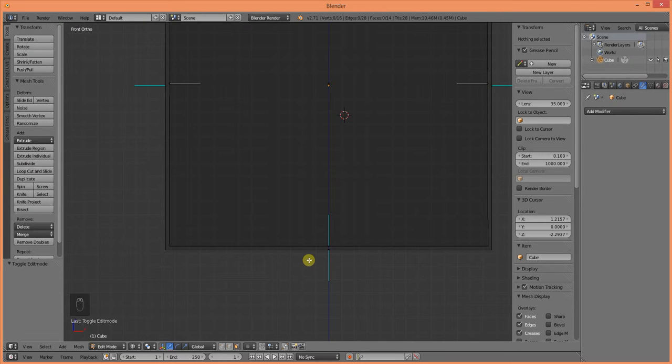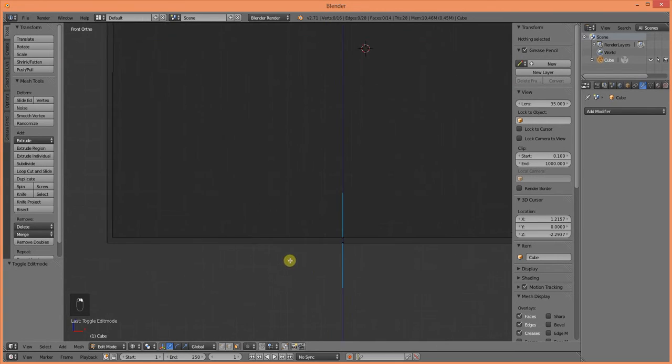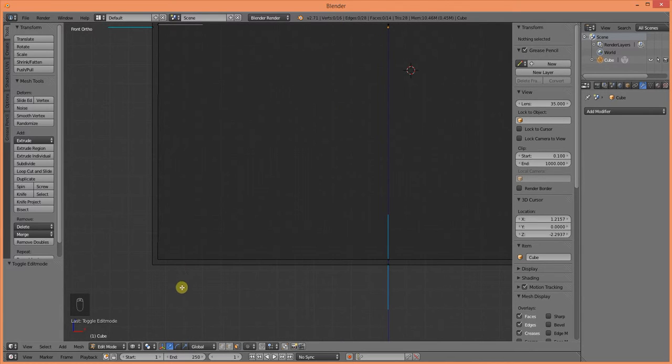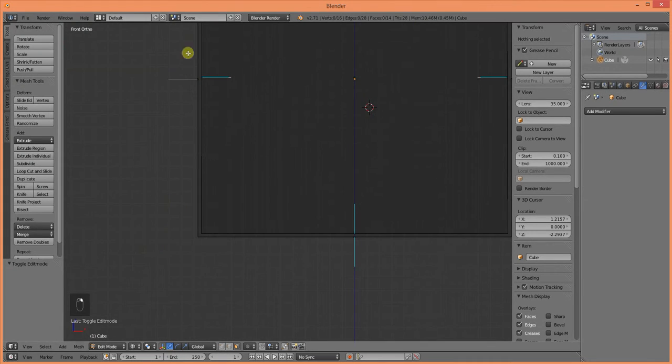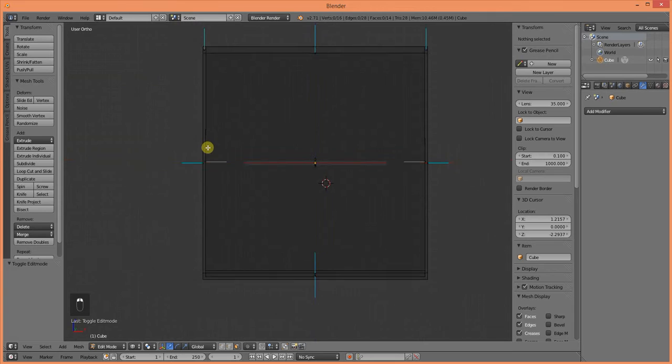But your layer height, you might be printing at 100 microns or 250 microns. That's just, you know, 1/10 of a millimeter. So 0.5 millimeter. So you're going to be printing 5 layers at 100 microns down here at the bottom, and then however many it's going to take to get to the top.